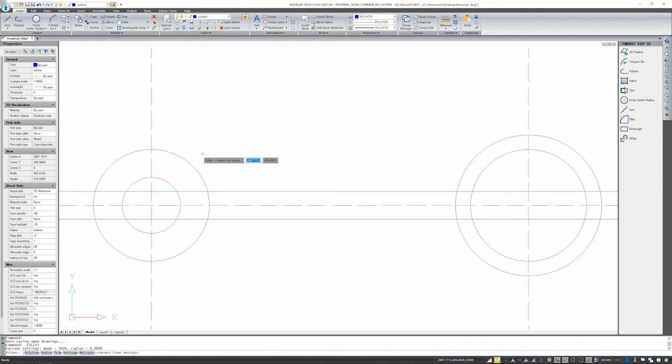Of course, you can also choose this option either from the Start ribbon or from the Edit ribbon, depending on what you need. If someone has such elements removed, for example, onto toolbars, then of course you can also activate them from there. We have the Fillet option activated, so we can define the radius of the rounding. Note that you cannot see the window next to the cursor, but on the command line you can already see that I have the settings.